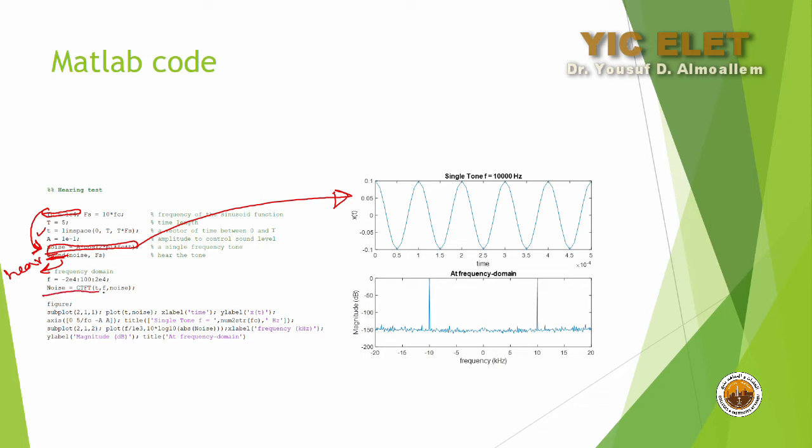Then I generated this m function for you, and this m function will calculate the Fourier transform for a continuous time signal. Once you create it, you will know how the signal looks in the frequency domain, and if you plot the result, you will get this one. And this is just to do the plotting.